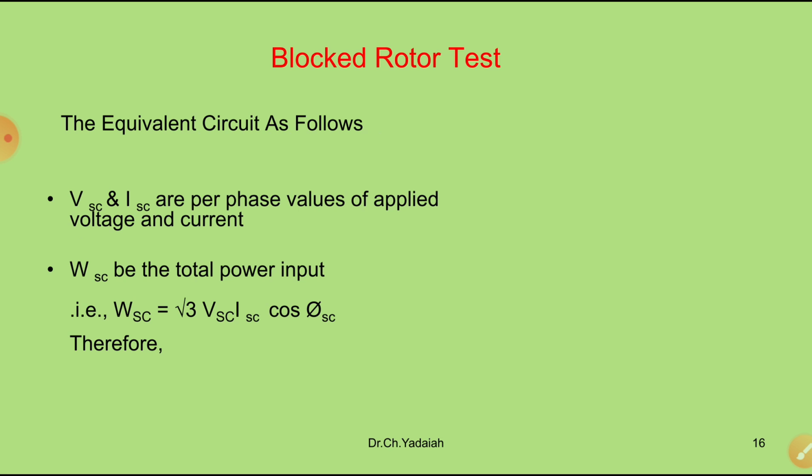The two wattmeter readings, taken with multiplication factors, add up to WSC, which is equal to root 3 VL IL cos phi, the 3 phase power equation.